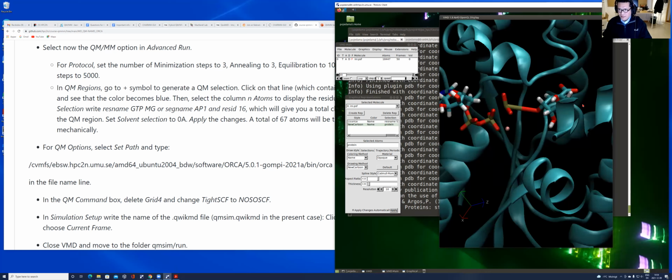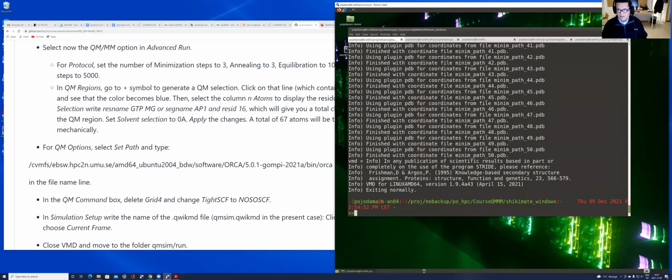But in the present case, I didn't set up the different windows for the free energy calculations. In NAMD, one can use the so-called eABF method, which I wrote in the chat, a type of ensemble method. This can be used in conjunction with the type of simulations that we have seen today. But this requires more time, and I haven't set it up up to this point.